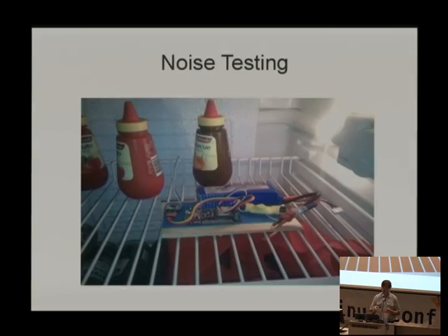So the next thing I did was I put that same little radio inside a steel casserole pot, completely enclosed, inside a microwave oven at the far end of the house, and I still got far too much signal and I wasn't getting down to the noise. So then I put a 30 dB attenuator that I got off eBay on the antenna connector, and then I was down to the noise level and I could start checking the error correction.